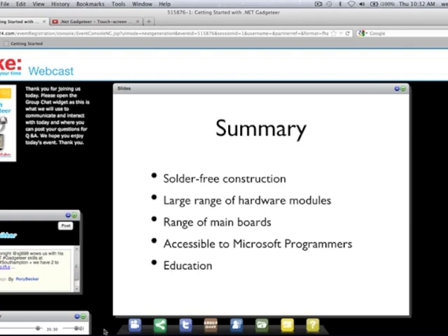Suresh, is it possible to do some home automation stuff with the Gadgeteer? Yeah, I think that's an excellent question. I think it'd be a very good vehicle for home automation, as well as the wireless modules, which obviously help a lot with this kind of thing. There are sensor modules. Seed Studio have quite a big range of different types of sensor module and also relay modules. So with the relay module, you can control quite high power devices and have the Gadgeteer switch relays on and off, which would in turn switch mains powered lighting on and off, that kind of thing.